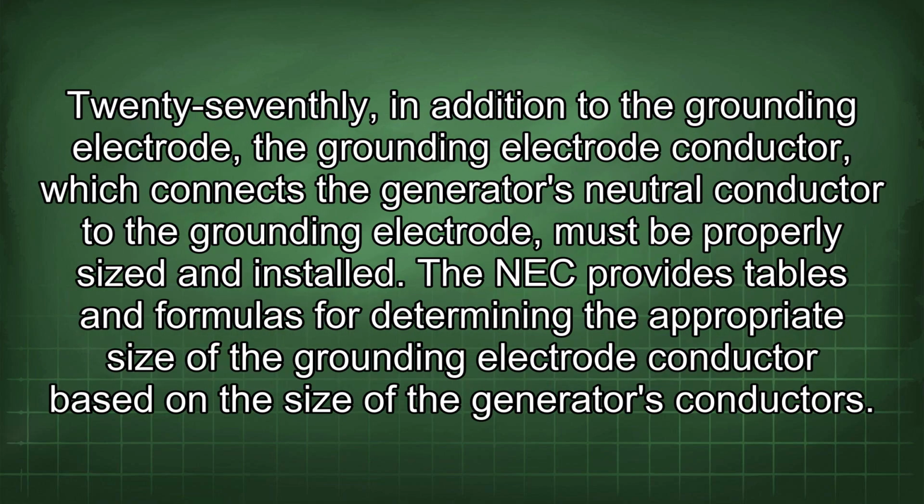27thly, in addition, the grounding electrode conductor, which connects the generator's neutral conductor to the grounding electrode, must be properly sized and installed. NEC provides tables and formulas for determining the appropriate size of the grounding electrode conductor based on the size of the generator's conductors.